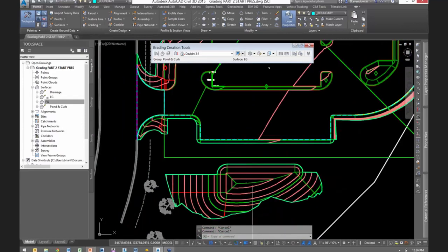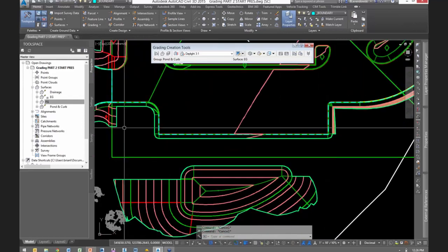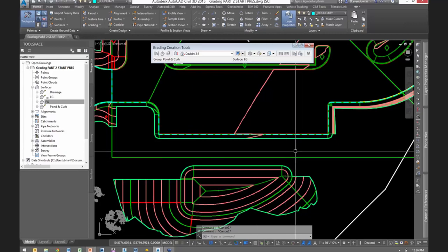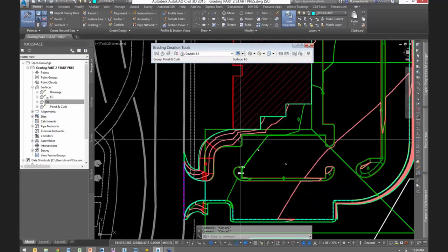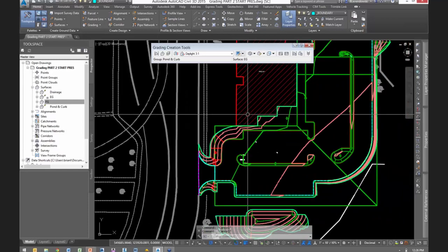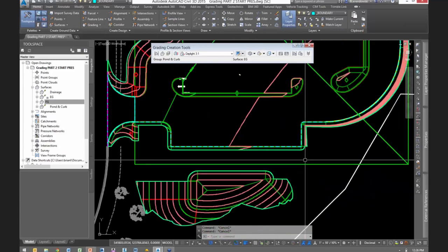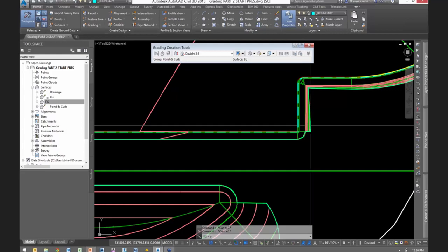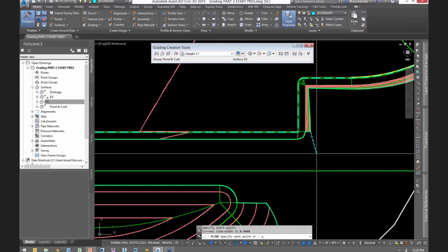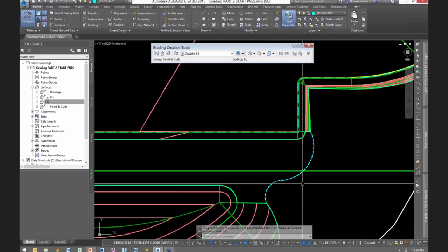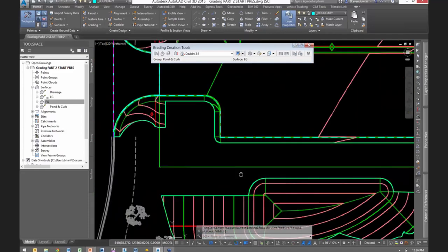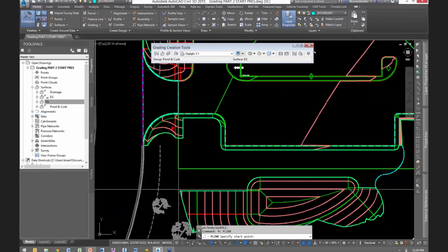All right, what else here? Got to finish up down here. Okay, we can't really put a grading between any of these items here because the grades are kind of random, like that grading between the building and some of the parking lot up here, what we saw. So we're going to do that same kind of thing. We're going to draw feature lines and then place an infill in the closed area. And I like to start with polylines because it gives me some control on that exact grading limit. So I'm going to draw 2 polylines here.